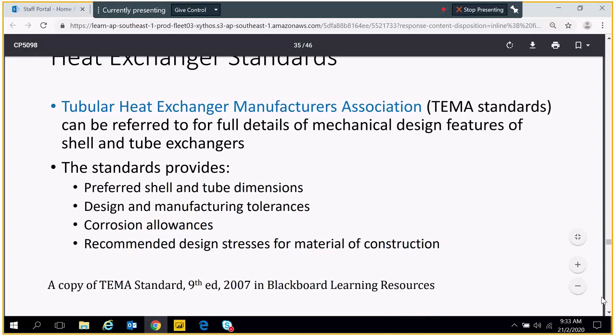The reason is that for your heat exchanger, there's a layout, all right? So you need to make sure that the layout is not awkward. Think of people who are trying to install the heat exchanger at the plant site. So we should at least not make the layout awkward. When the layout is awkward, then how about the piping? The piping must go around the heat exchanger in a very awkward fashion.